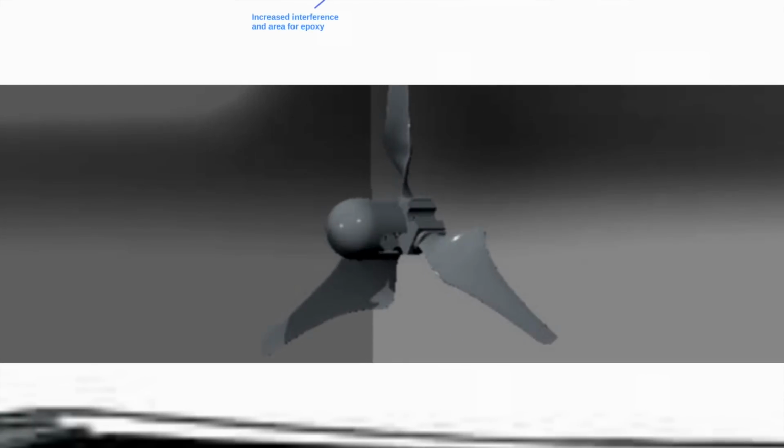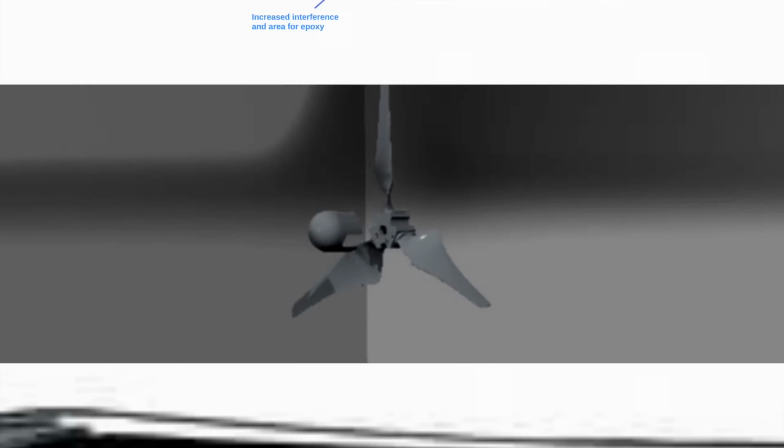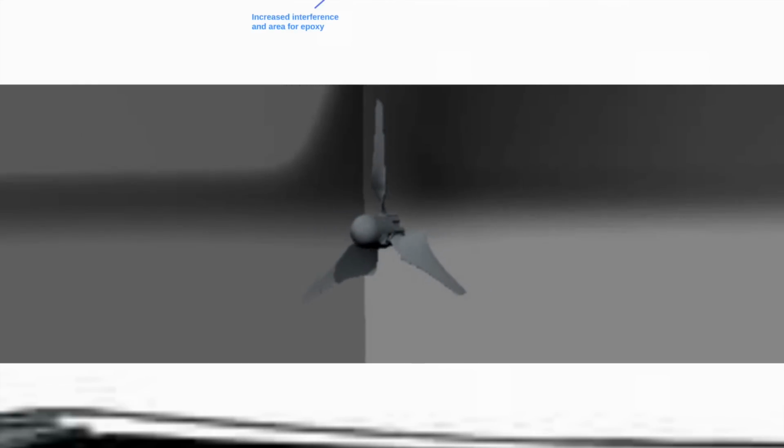Following the assembly of our wind turbine, each blade is locked firmly to the hub by a bolt. This fixes the angle of attack. The design requires individual removal and assembly of each blade onto the hub, which in turn allows the blades to be glued, finished, or even replaced individually.